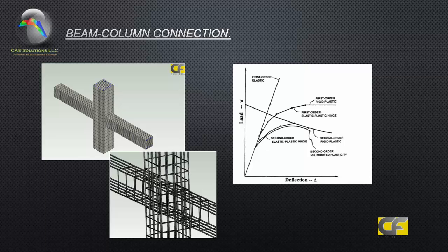When we take into consideration the P delta effect, we know that it must be modeled, as it can ultimately lead to the loss of lateral resistance, what is called ratcheting. This is a gradual buildup of residual deformations under cyclic loading. Large lateral deflections magnify the internal forces and moment demands, causing a decrease in the effective lateral stiffness.